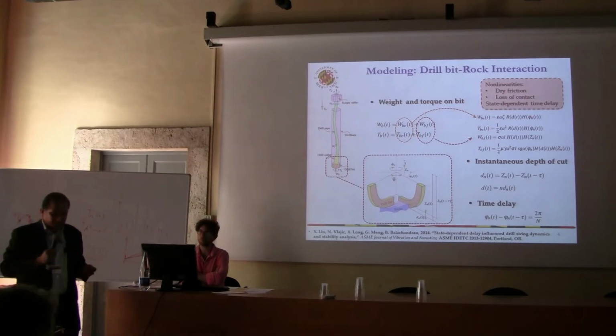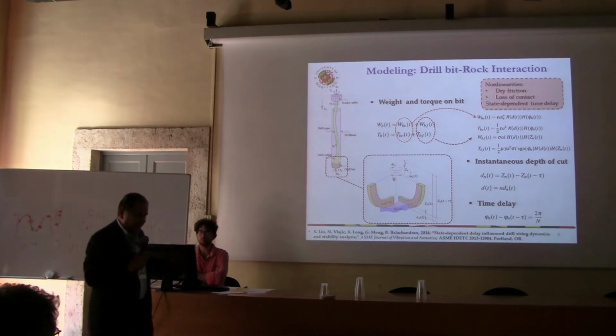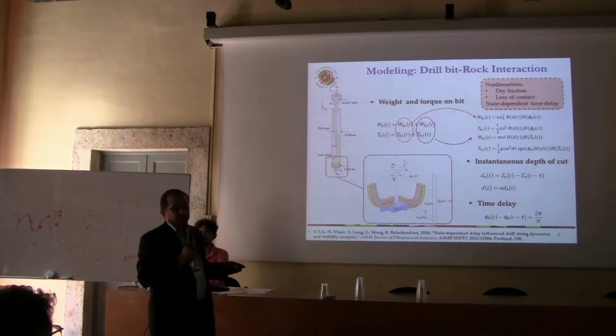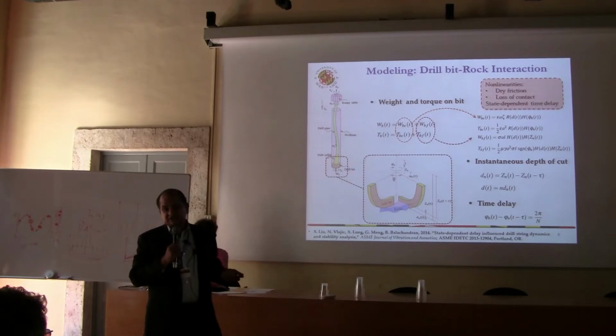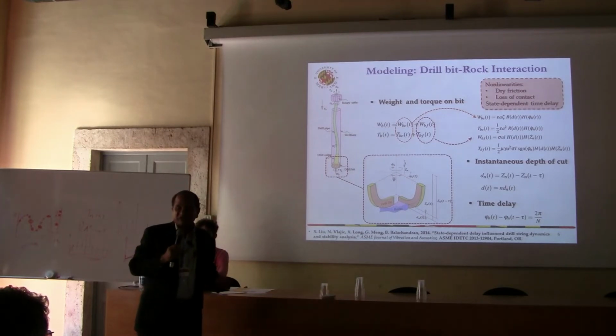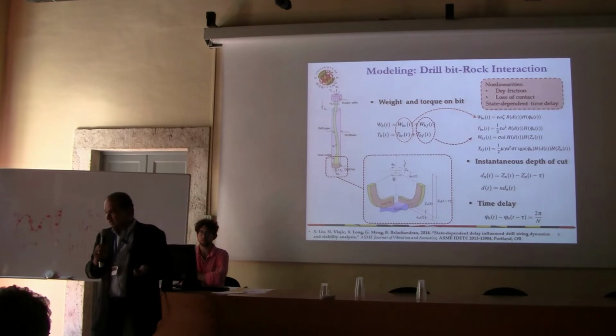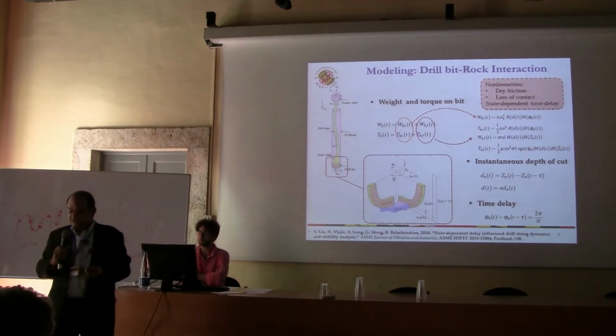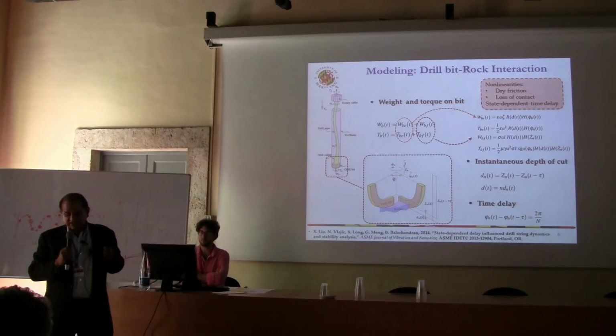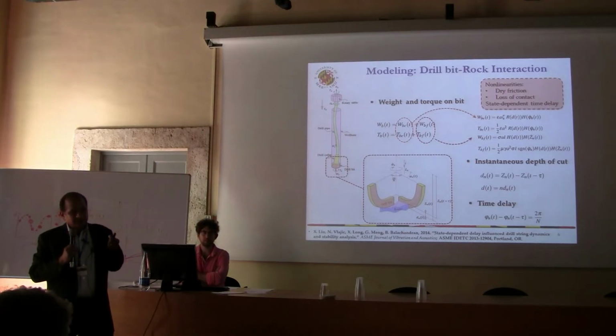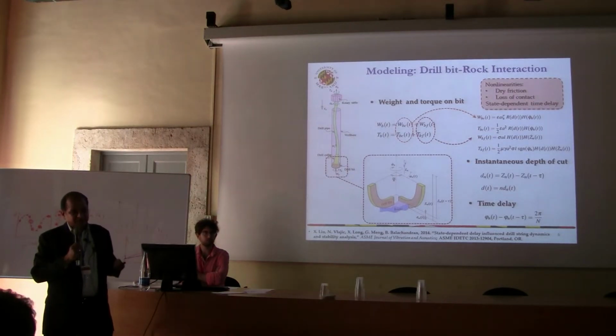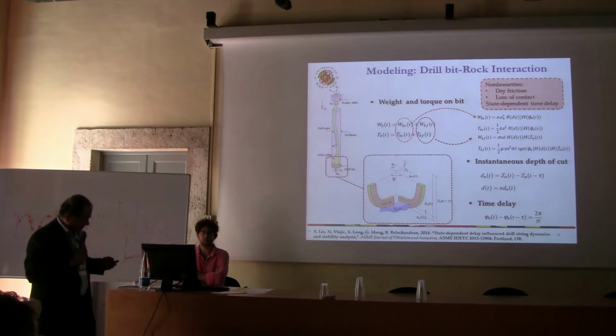State-dependent delays are not unique to drilling processes. You could also have them in milling, in additive manufacturing, and in other places as well. But with a state-dependent delay, stability analysis does get difficult because a true linearization does not exist. So one has to come up with approximations to provide the local properties of that particular delay.